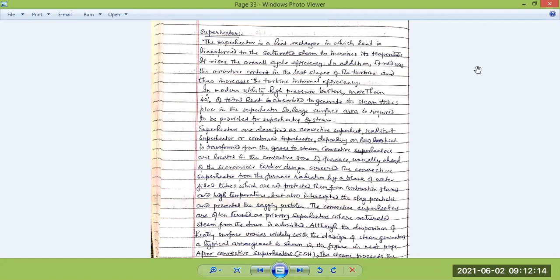So everywhere, heat transfer is only three processes: conduction, convection, and radiation. Mostly convection, and from one form to another, the heat is being transferred from the flue gases surrounding the riser tubes, which are kept surrounding the total walls of the furnace itself. The majority of this heat is transferred to the riser tube by means of radiation.